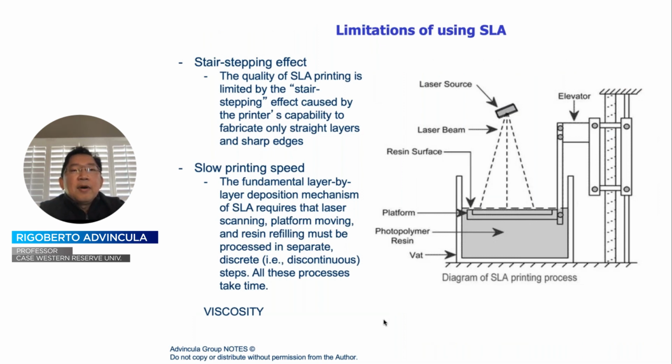So what are some of the limitations of SLA? Well, one can either look at this as a weakness or a strength in that there's a stair-stepping effect with SLA. In other words, the fidelity of each layer are basically steps or stairs that can lead to a poor resolution, actually, or even different types of incapacity to produce edges or different types of geometry limitation.